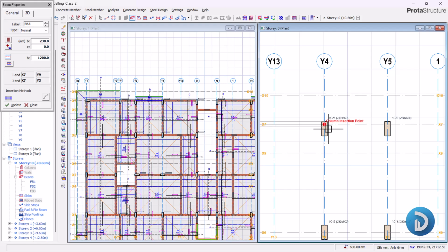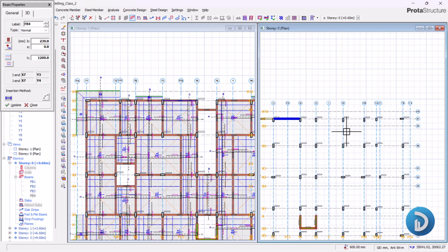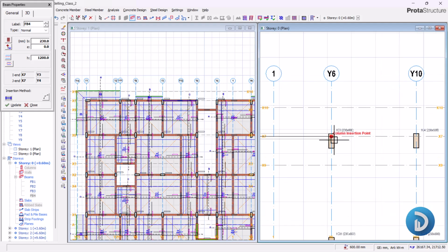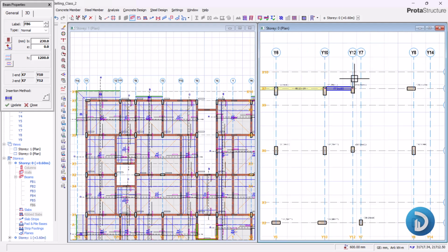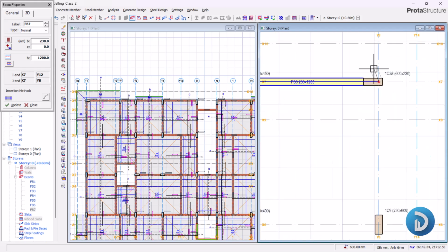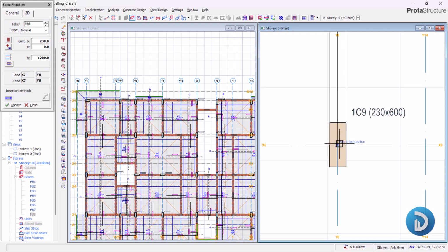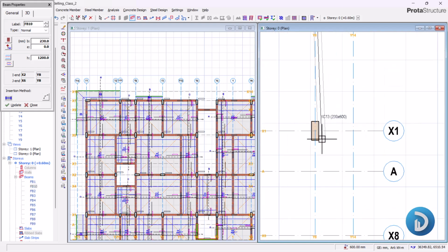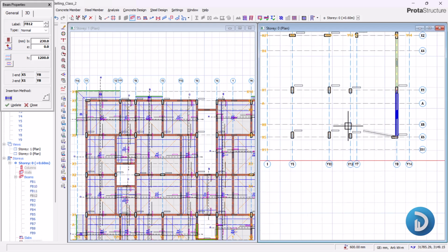I'll put this here as well. Okay. Then I will continue because we've gotten to this part. So I will continue from here to this one. Okay. It is advisable that you place these beams from column to column, all right, especially when you are designing a raft foundation or cases where you have interconnected grids.